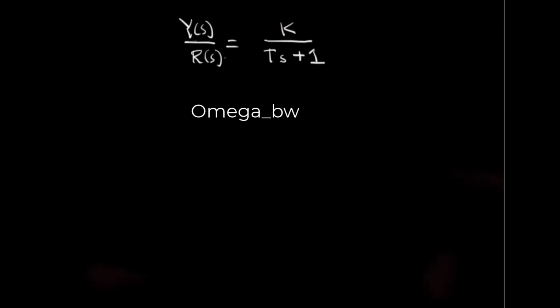So in our last video, we learned about time constant tau, and I mentioned that it's very important because it helps us to understand a very important concept in control systems, which is called control bandwidth, or the bandwidth of the control system. So I said if you have the first order control system, as I show here, this is a static gain and this is the tau we're talking about, which is measured in seconds.